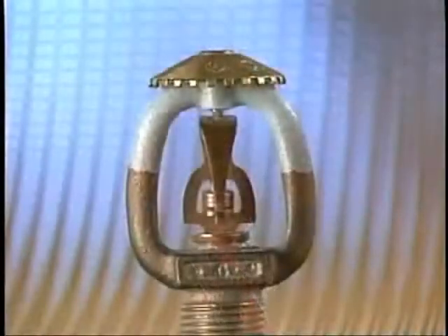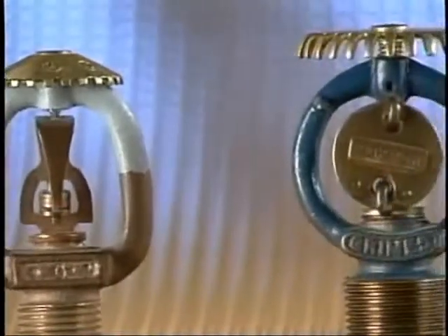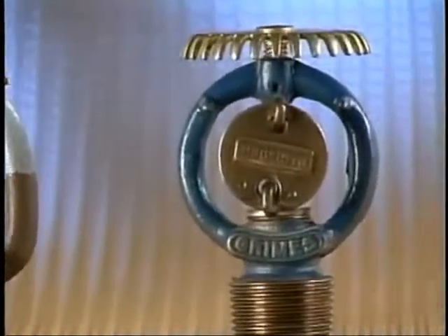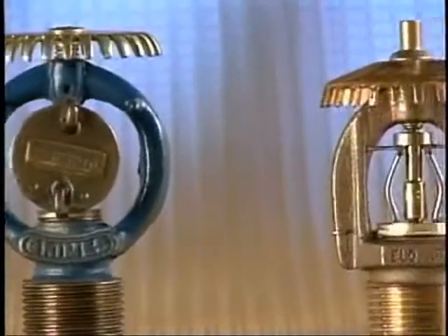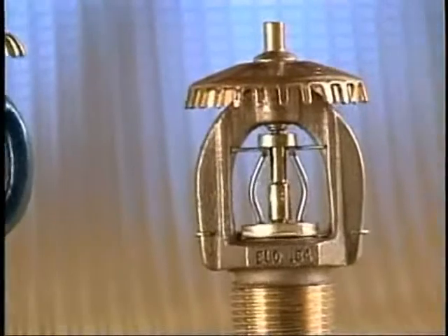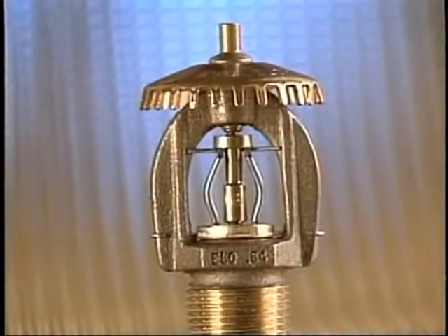There are 3 types of standard sprinkler. All of them are defined by their orifice size. Half-inch, which is the oldest, 17/32 inch, which was introduced in the early 60s, and the ELO, or extra-large orifice sprinkler, which was introduced in the 1980s. Basically, the ELO sprinkler is an improvement on the 17/32, which was in its day an improvement over the half-inch. In terms of standard sprinkler evolution, the ELO represents the latest technological refinement.